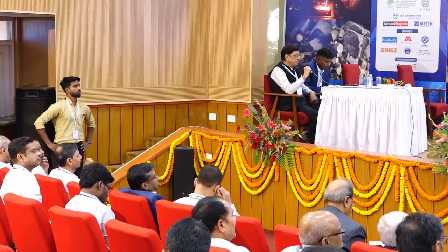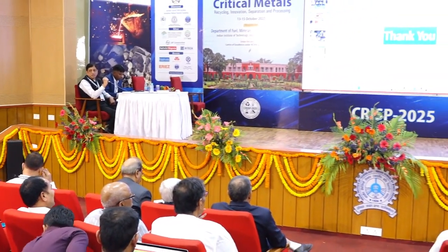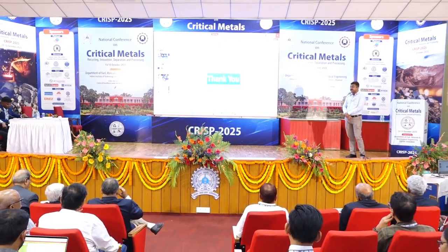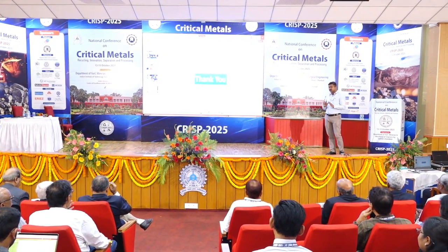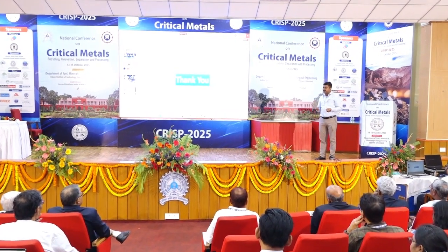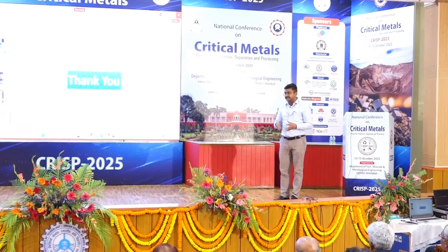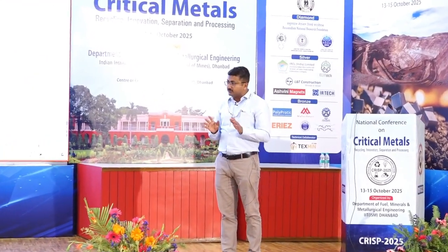The basic advantage with hydrometallurgical processes is that you are going to leach everything into the solution. So rusting of the magnet is not a problem as long as you have sorted it properly. Rusted magnet dissolution is not a problem, because in our process we are purposely adding some nitric acid. Nitric acid being an oxidizing agent can dissolve all the rusted type of magnet also. So there was no residue.